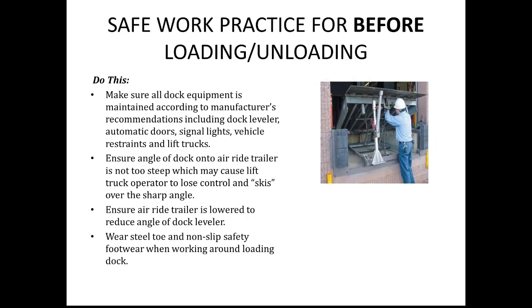As an employer, you're responsible to make sure the dock plates are working properly, as are the doors, the restraints, and any signal lights. Also, you want to make sure the angle of the dock into the air ride trailers is not too steep, because if it is, sometimes you can get spinning or skidding inside the trailers. And similarly, if you got an air ride trailer, you want to instruct the driver to drop it and bring down the angle so that the dock leveler doesn't have a high rate of climb.